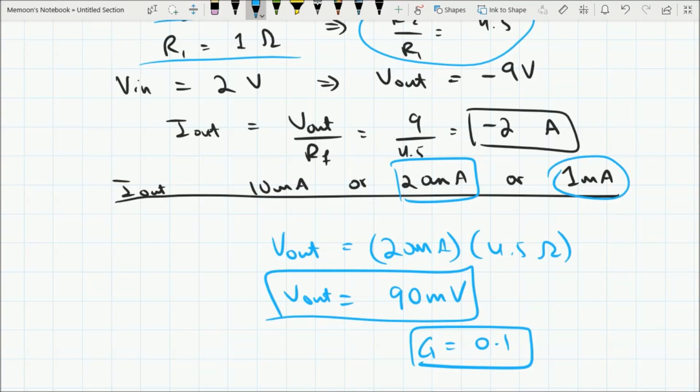So what you will be doing is using your signal from your sensor or transducer, converting it to different levels, and implementing some different equations on that input, and converting the type of input to another type of input. For example, you will be converting a change in resistance to a change in voltage, or a change in voltage to a change in current, and vice versa, using these operational amplifier circuits.